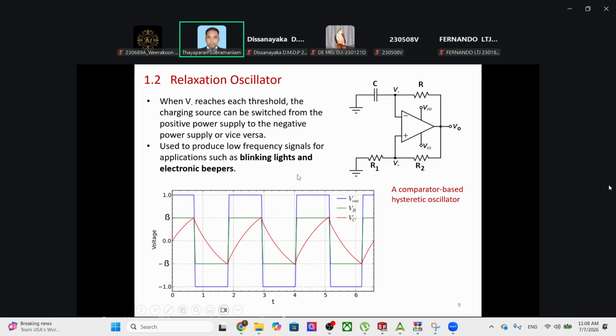Therefore, you have to pay a little bit of attention to this matter also, because it doesn't bring you any goodness in the circuit. When you have plus or minus 5% tolerance components, if you go for an amplifier with 0.1% accuracy, probably it is easy for your calculation, but the output performance doesn't make much sense.